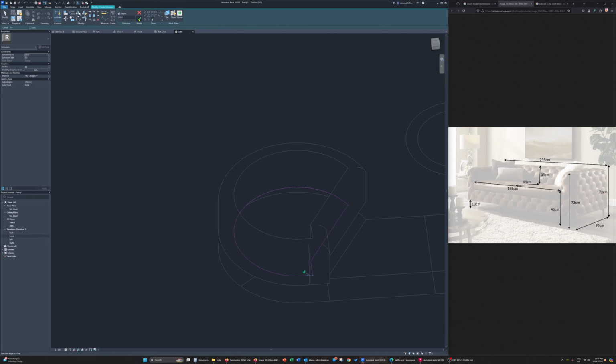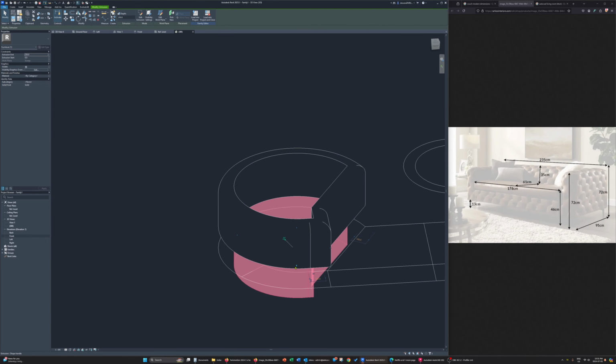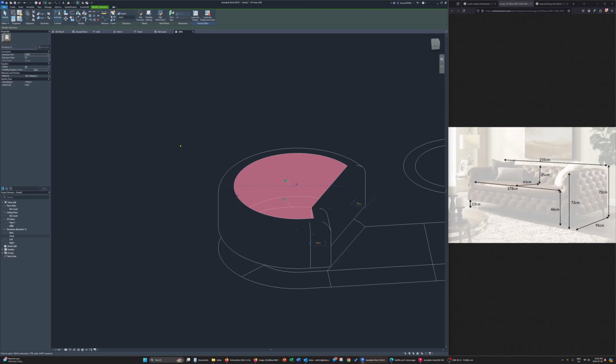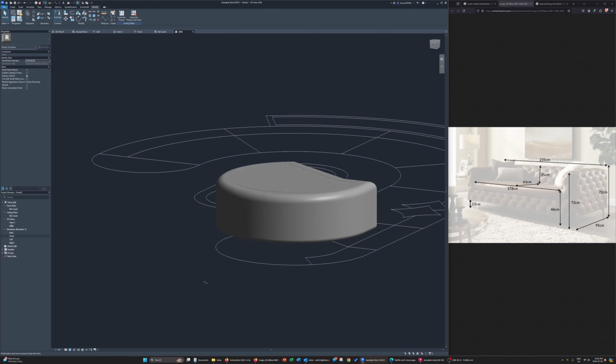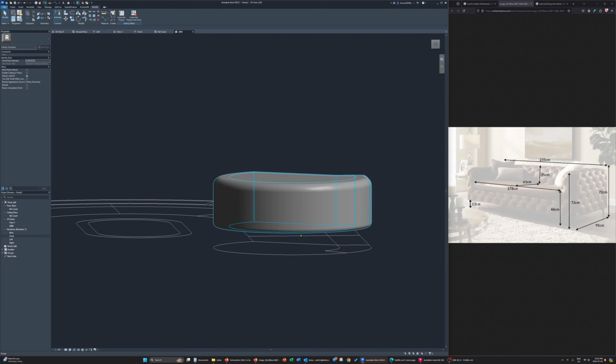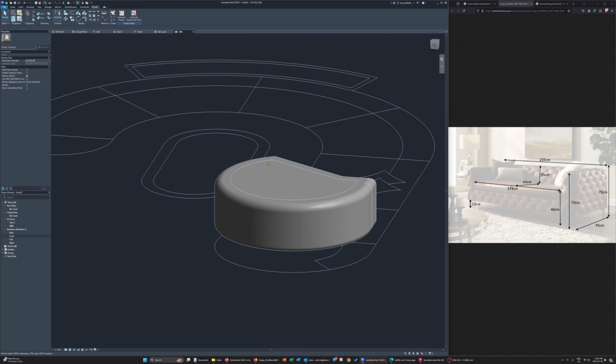And once again, we can kind of see where this is coming. I'm just going to align this perfectly to here. So now, while you don't see perfectly well, you can kind of see we've created this nice little rounded object. If I had created an extrusion from the start, it would not have been the best thing, because I would have been creating a square object almost, very 90 degrees, not nicely rounded edges and things like that. Instead, I'm using a manipulation of sweeps and extrusions.